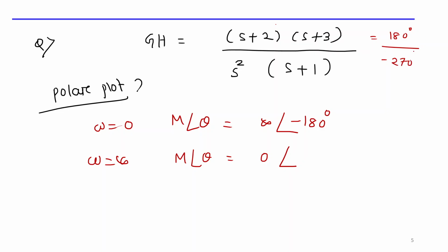So which one is the resultant? Resultant is -90. So this value is -90, and it is the sum of poles and the sum of zeros; the resultant you have to take. Previously only poles were there, so you were only counting the poles, but now zeros are coming into the picture, so you have to calculate the equivalent number of poles and zeros. So 2 zeros contribute 180, 3 poles contribute -270. What is -270 plus 180? Just add these two, and it gives you -90.